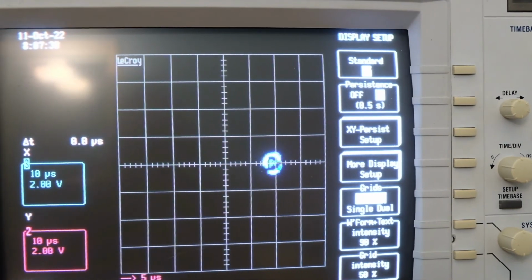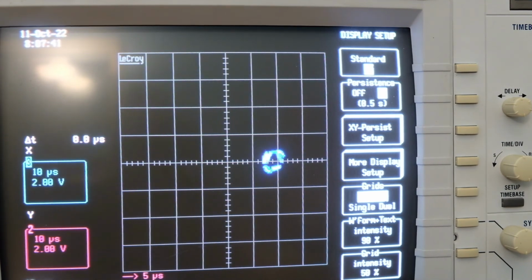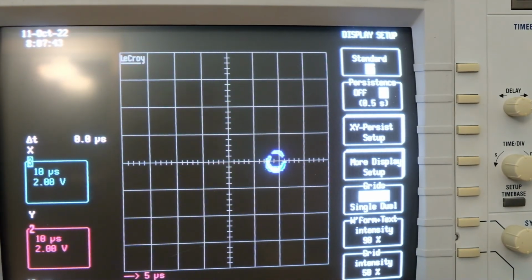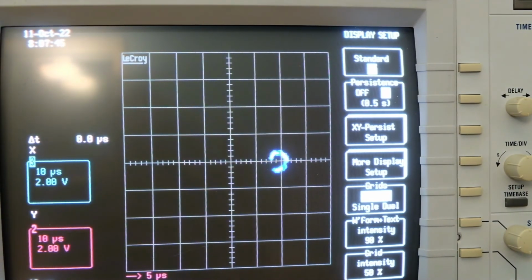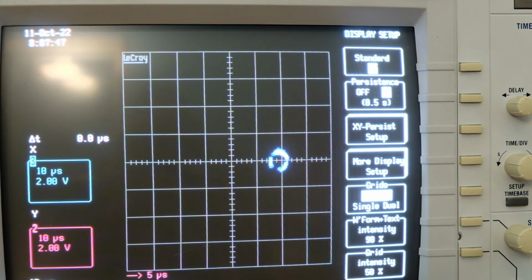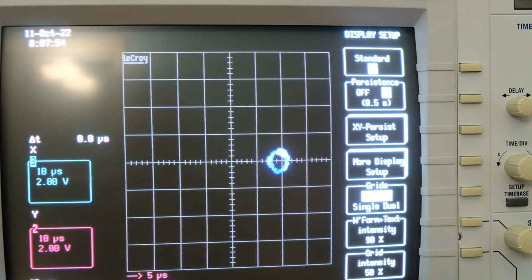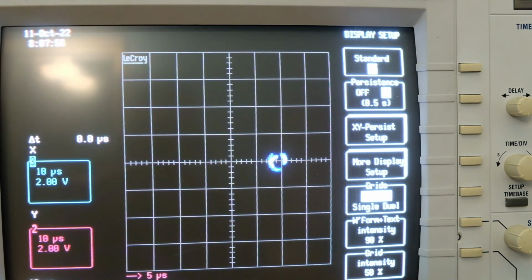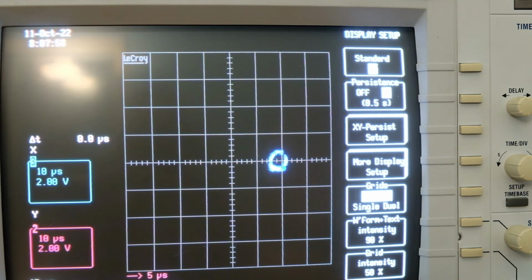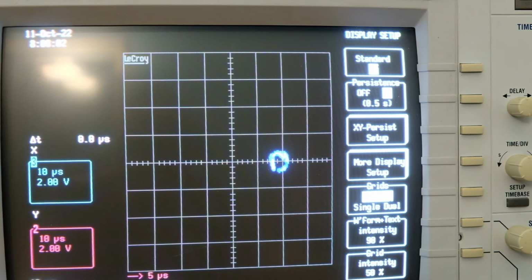I'm going to bring it to 1 millisecond, and you can see with the 5 millivolts there is quite a bit of noise, because I'm using an external mixer to add these two voltages, and there is some other kind of external noise also feeding into this, which is causing the lock-in to have a much larger spread in terms of the noise.